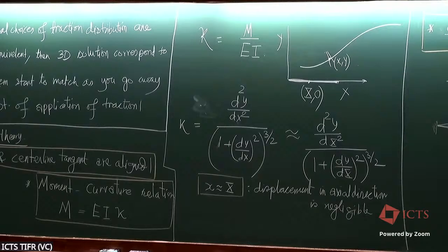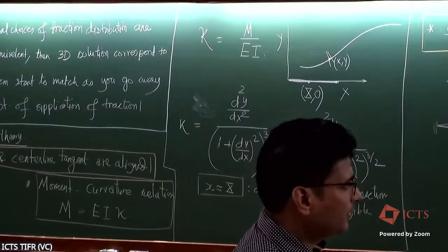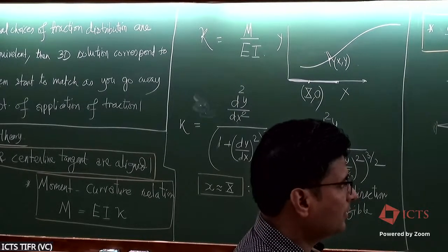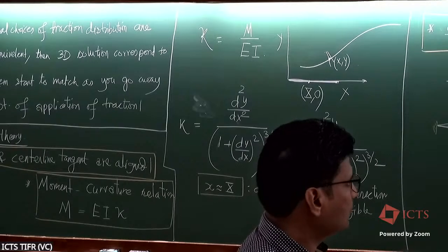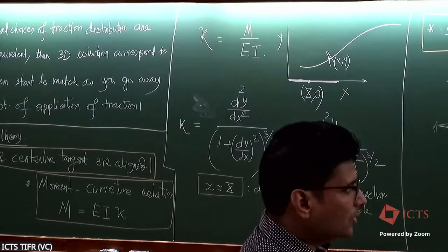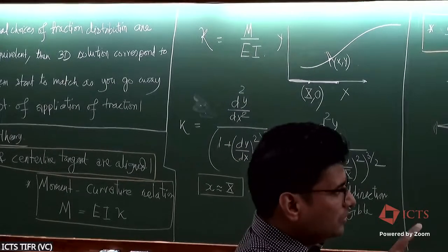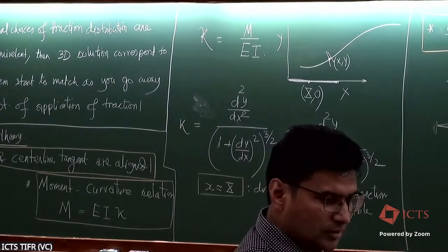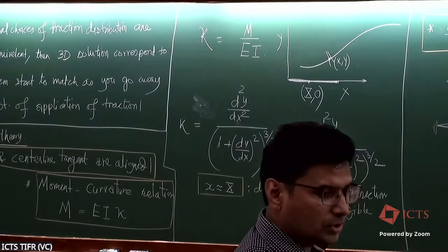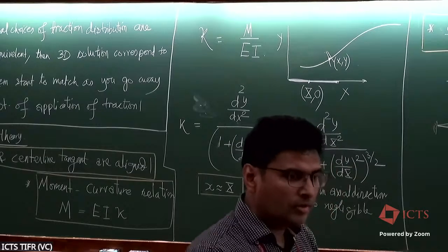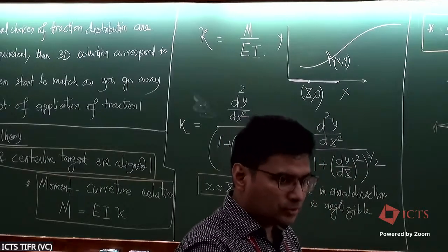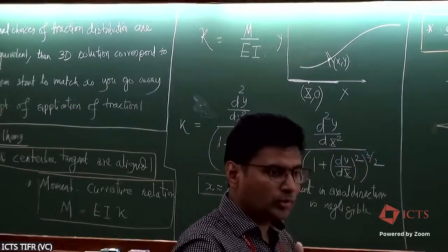Maybe we got two questions. Yeah, sure. One is, what is the relation between G, the modulus G, A, E, and I? Is there a relation between them? A is a geometric property. A is the cross-section area. G is the shear modulus of the material of which the rod or the beam is made. So it's proportional to E. It depends on the Poisson's ratio, for example, G is equal to E over 2 times 1 plus nu.